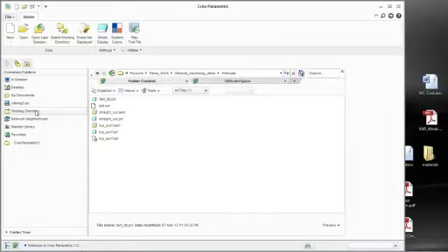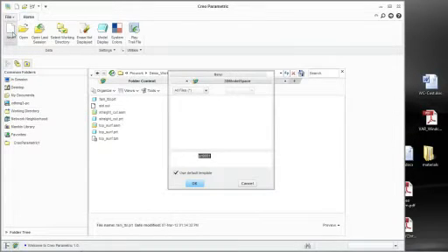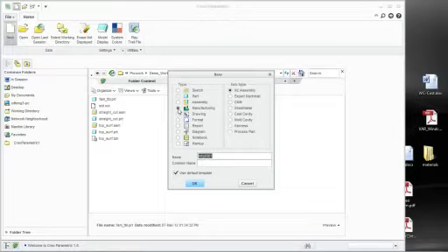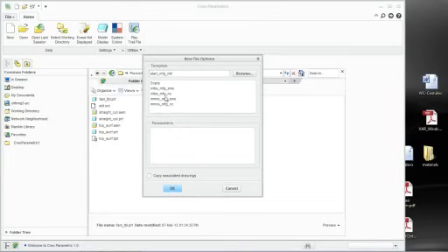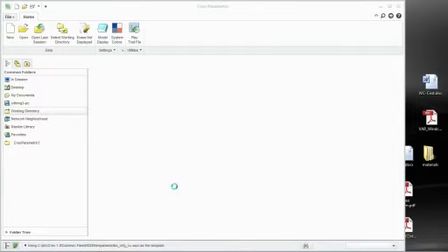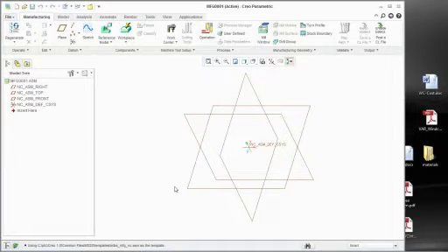Now, a lot of times when you go into customers, or at least when I go into customers, and they haven't had a whole bunch of guidance on how to start it up and get things going, for those of you that are using the software, when you say File New and you do hit the manufacturing button, and I have to do this because mine's set up a specific way, when you start a toolpath file, an actual toolpath assembly, essentially what you have here is really just an assembly with manufacturing ideas on top of it, okay? And what you have to create is this manufacturing environment to start out with.